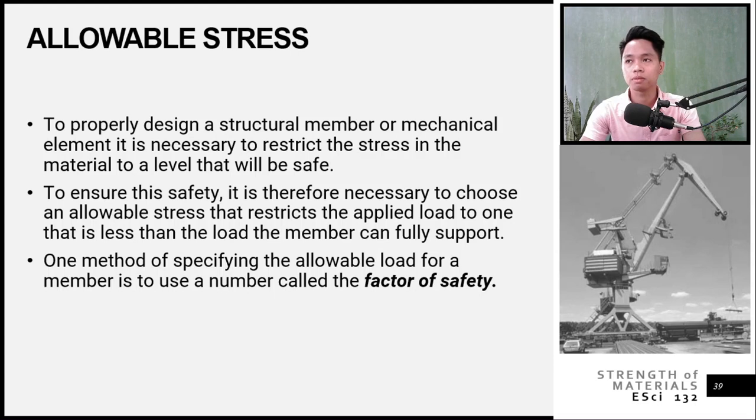No one's perfect. So because of that, if you have no allowances, instead of 400 it becomes 350, and your 250 becomes just 200, right? It changed. So it may affect your design. If you have no allowances, then it is dangerous. That is why for our designs we use the factor of safety, and what else,